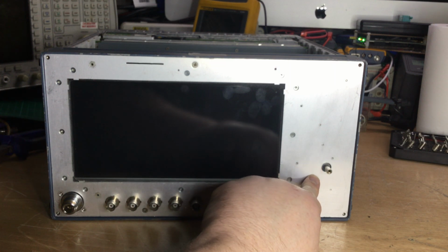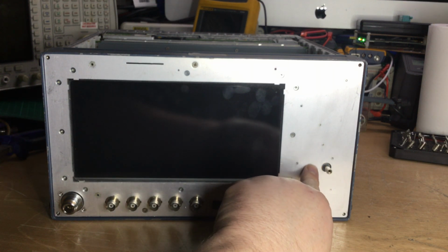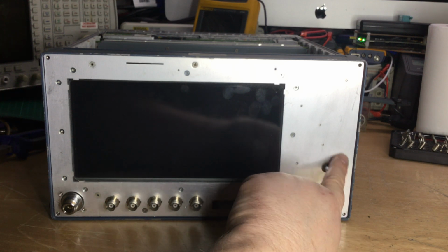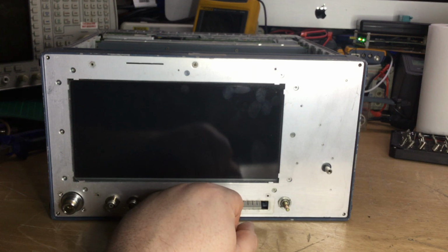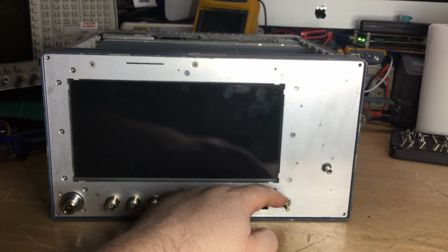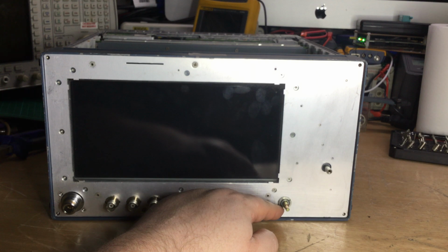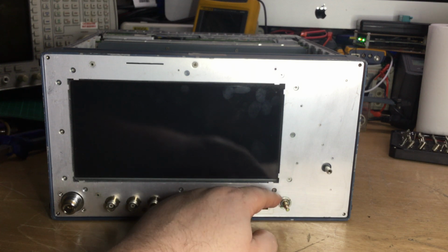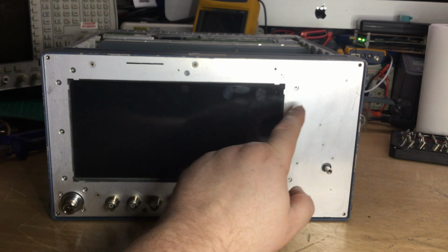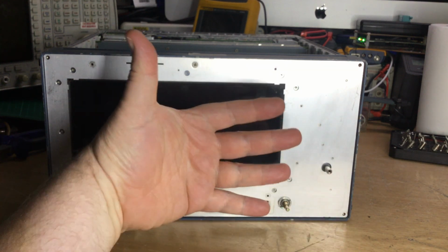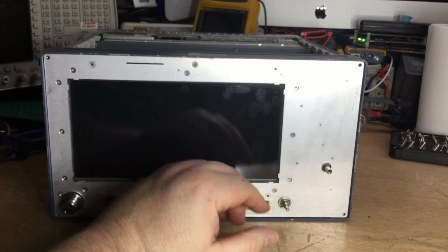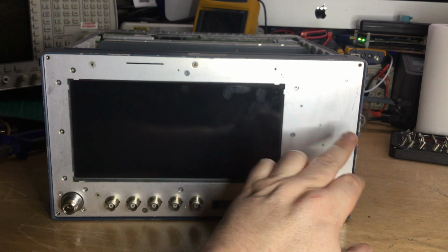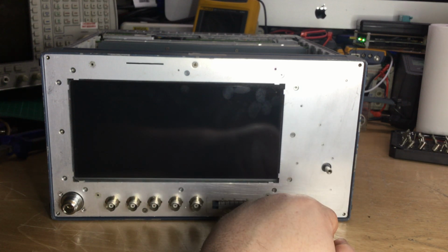but as you can see on the front as well, the variable control, there's no actual screws on the front of here that fasten this to the front panel. It's done from the other side, so we have to undo this collar here for the volume and the contrast control, because that's on the same PCB. So once we withdraw the front from the unit and turn it up, then we'll be able to access all the screws that fasten the variable control.